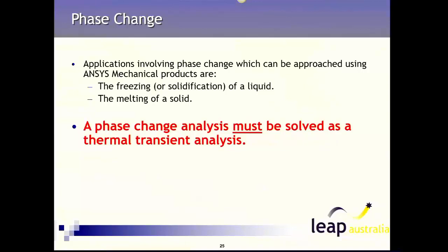Any applications that involve phase change, so again, solidification or melting. If you're simulating, say, a casting, where you're having a metal change phase from liquid to solid, you want to make sure that you don't get any chunks that are all solid before everywhere else. You don't want to have parts of your device that you're solidifying, freezing and trapping all the liquid underneath, because it needs to expand or contract, and that will cause all sorts of problems in your casting.